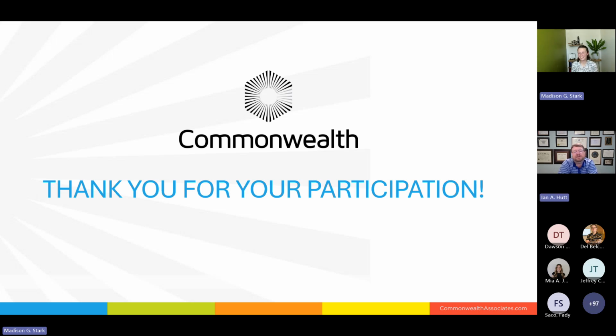Yeah, one point to make note of too. Yeah, very good point, Madison. As we're getting into some components a little bit, when we have an ungrounded system and you have a line to ground fault, what ends up happening in that system, and this will be from maybe your three-phase power classes, either in your master's program or your bachelor's program, is that because there's no ground system for that current to flow through, you see voltage rise on the unfaulted phases, and that voltage rise can be square root of 3.